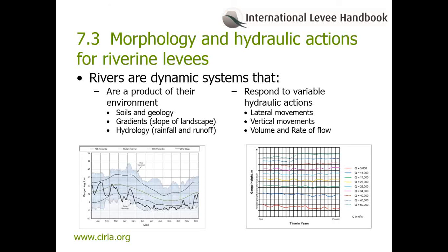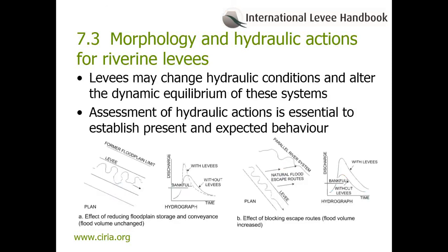This could be a result of lower stream capacity due to sedimentation or increased roughness. It could also be a result of levee construction downstream of the observation point. It would be necessary to expand the investigation to characterize the source of such a change.